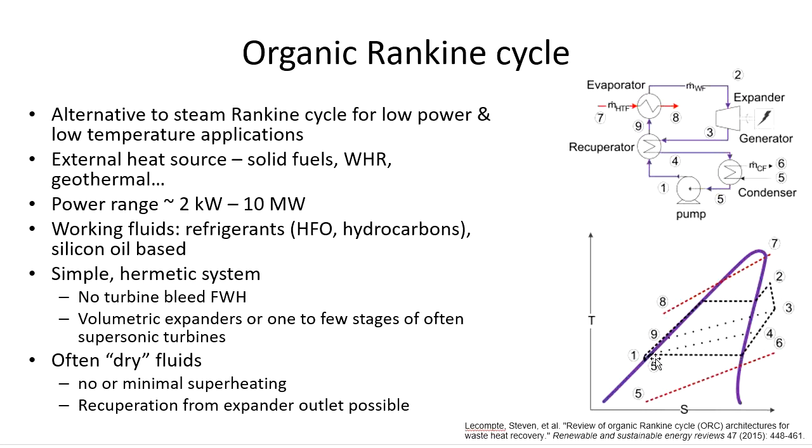At the end of the condenser, some subcooling might be necessary, either for net positive suction head for the pump, or generally from the principle that it's unlikely that the last molecule of vapor would use the last portion of the heat to condense, so the heat transfer in the condenser would work in the way that the end of the condenser would just be slightly subcooled.